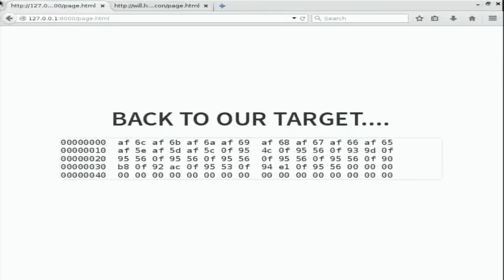And if we go back to our sample, and this is the first time I've shown you the actual sample we had, well, what do we see right at the start of the file? It's a pattern of what I would call stride 2, a stride 2 pattern right at the start. 2-byte chunks that are self-similar on a 2-byte boundary, followed by a series of 3-byte chunks that are similar on that pattern. And if we assume that all of this is a vector table, well, it'd be a bit of an odd one, because you don't normally see a vector table that has different sized elements in it. It would be harder for the processor designer to implement.